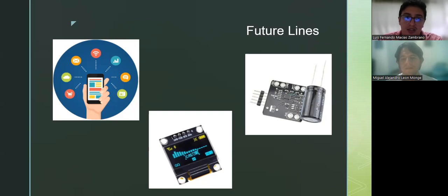For the devices used in this project, we use commercial devices that are not specialized to power all the devices we use. So in the right picture, we can see a very integrated solution for the charge of the batteries using the solar panel. That we have to use a Schottky diode and PMOSFET to switch the load and the charge of the battery, and this integrated circuit does the same by itself,